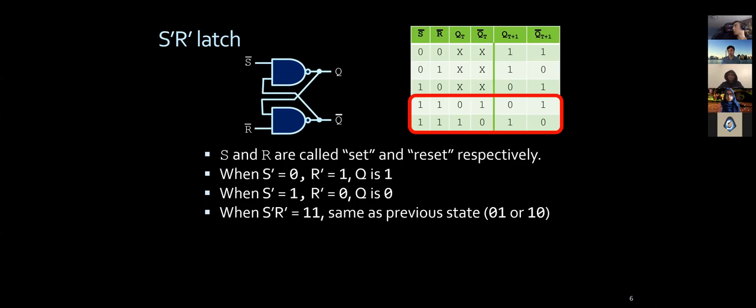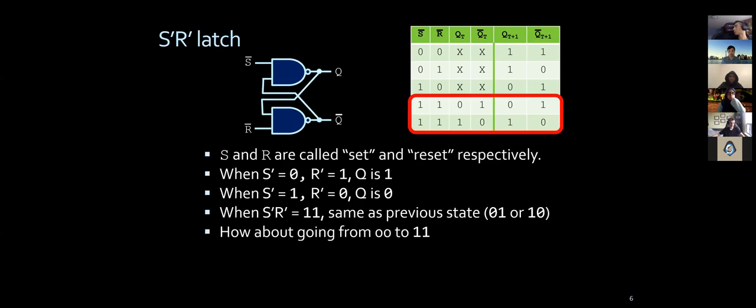Someone on Piazza asked: we build these latches and flip-flops, but how do they really store the memory? This is the way they store memory. They store a state that is persistent by manipulating the inputs of the cell. If I try to build a memory based on SR latches or more advanced cells, I can give it certain inputs. If I want a memory cell that has 1 in it, I can enter certain inputs into SR, then lock it into this value, and later I can read this value by sensing the output. This is a very high-level description of how we can get memory out of it. It is not going to be very efficient memory, but it would work. Those are conceptually the building blocks for memory.